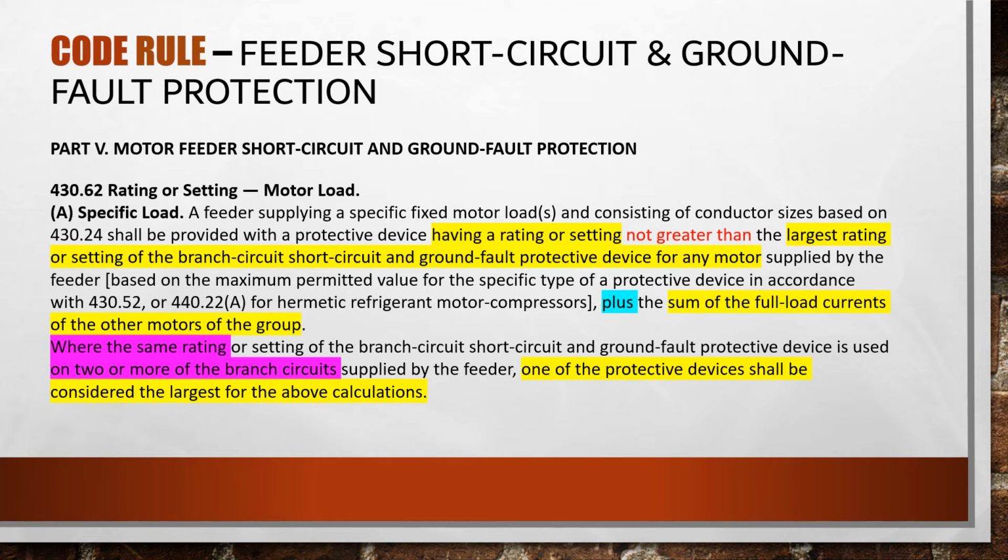And also in case all motors have the same rating or setting, we have to consider at least one of them as having the largest rating. So we can use it in the same calculation.